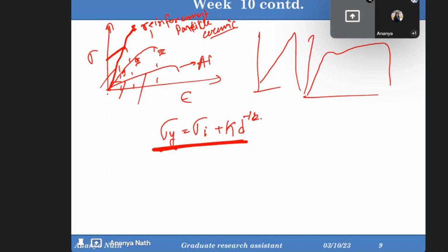We mix the alloying element in such a way that it will have a larger number of facets, and those facets will have less lattice mismatch with the parent atom. Then only those facets will act as the nucleating site. So if you are mixing a nanoparticle that does not have sufficient facet surface area from which the next grain may nucleate, then it will not act as a grain refiner, and the strength will not increase. So it's like that.